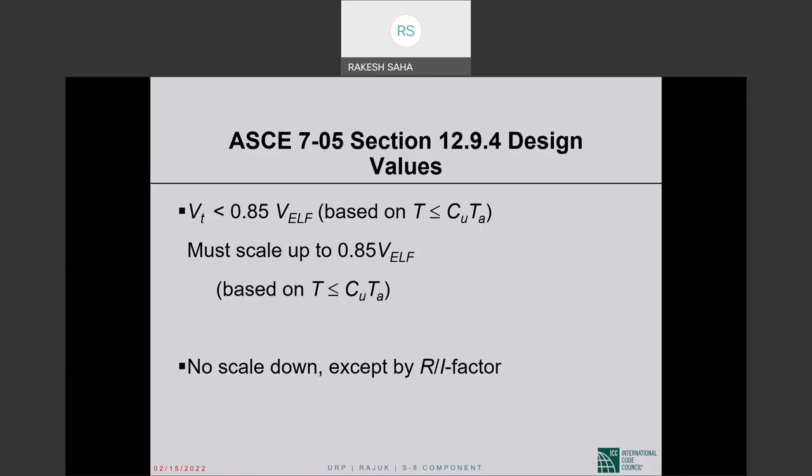Let us say the dynamic base shear is 100, 85% of the static base shear is 135. So you will amplify all response quantities by the factor of 1.35. That is the scaling that we are talking about.